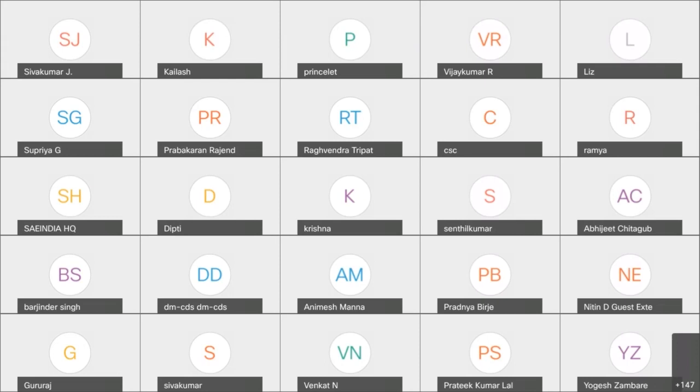The other thing is the timing and execution related aspect. The problems with timing and execution are livelock conditions, deadlock conditions, blocking of executions, along with the sequence of data and timeouts. Those aspects also get affected. For that, you will have a proper scheduler, resource management like semaphores and mutexes, the program sequence counter, and along with the watchdog you will also monitor the program sequence and timeouts. Through this you can address the timing related aspects.